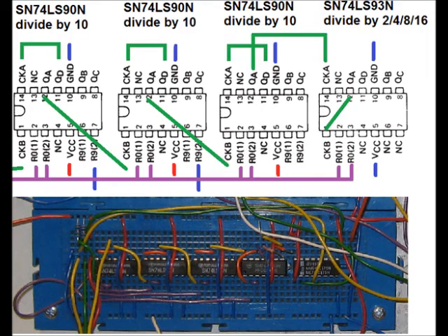The solution is a frequency divider to choose a division between 2 and 16,000. This has the advantage of preparing a speed measurement that divides the measure time by a certain amount of signals. To analyze the current direction, a data flip-flop is used which can deal with frequencies up to 40 MHz.